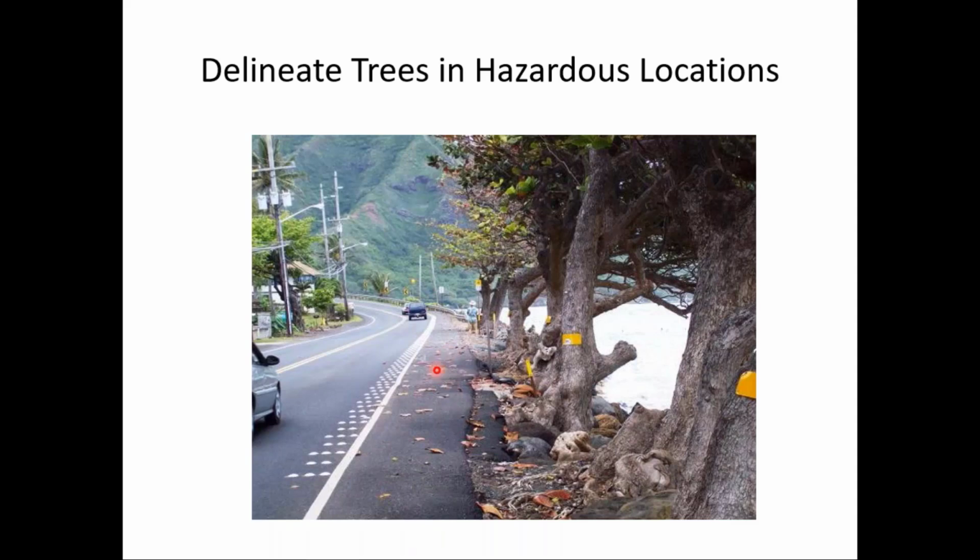Notice they have a paved shoulder. What's that? Maybe 4 feet or so roughly. And then they use these ceramic buttons or dots. They're kind of domes, if you will, dome shape, as sort of a rumble strip, I guess. It has a rumble strip effect. I don't think we could use these in much of the area that we have folks attending today from Ohio, West Virginia, upper Midwest. These are certainly not snow plowable. In our case, we probably want to use a rumble strip, but in this part of California, they don't have to worry about plowing snow, so they use these ceramic domes, if you will.